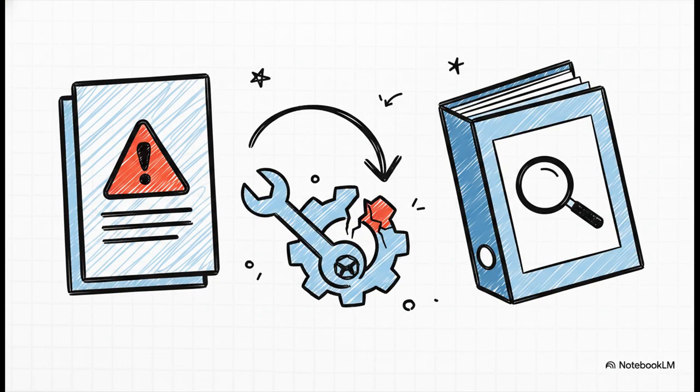And these tests, they aren't just random spot checks. They are heavily dictated by comprehensive inspection and test plans, or ITPs. Now, what happens if, say, a slump test fails, or the plastering just doesn't meet the standard? That's when we use non-conformance reports, or NCRs. The NCR officially documents the defect and rigorously dictates the exact rework procedures needed to fix it.